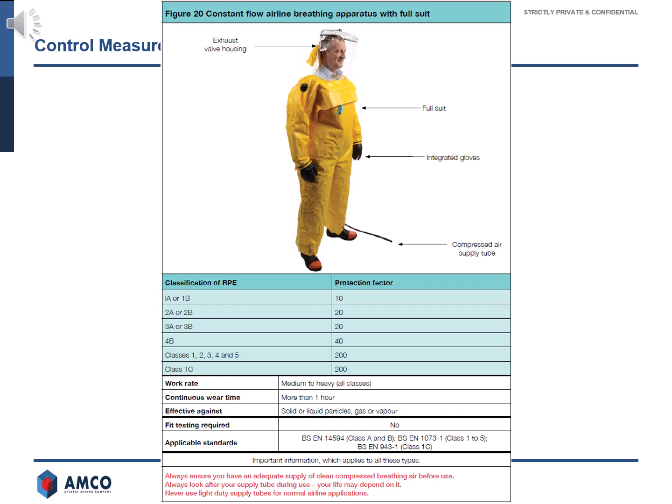Class 4, protection factor of 200. Work rate, suitable for medium to heavy tasks across all classes. Continuous wear time, recommended for more than 1 hour. Intended use, effective against solid or liquid particles, gas, or vapor. Fit testing, not required. Standards, complies with BS EN 14594, Class A and B, BS EN 1073-1, Class 5, and BS EN 943-1,